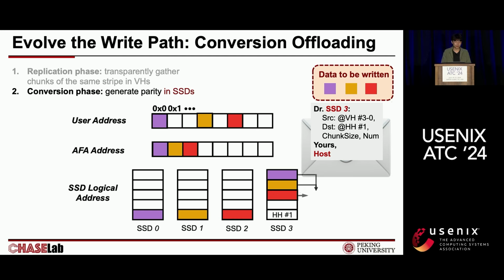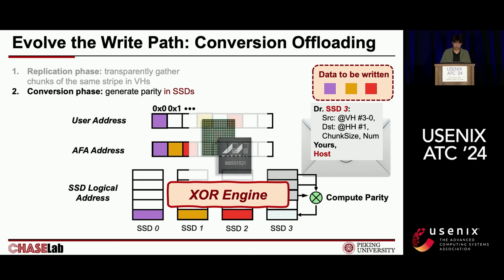The SSD controller reads chunks to its internal DRAM. It then computes the parity chunks and writes them back. Finally, the SSD cleans the data in VHs by marking the flash pages as invalid. Note that the parity computation can be done with the available SSD internal XOR engine, which is originally used to compute die-level parity within SSDs.